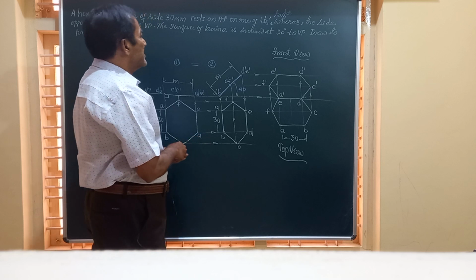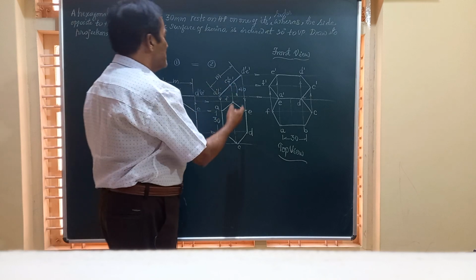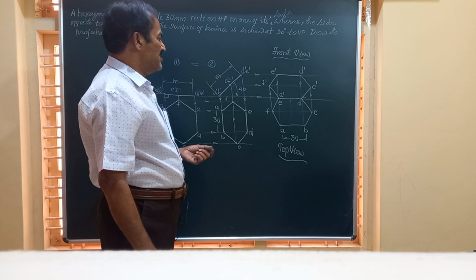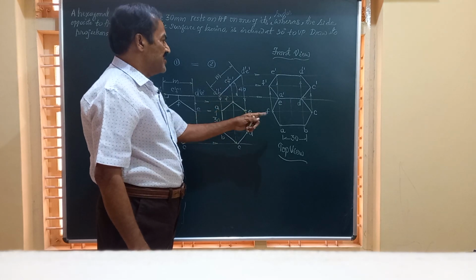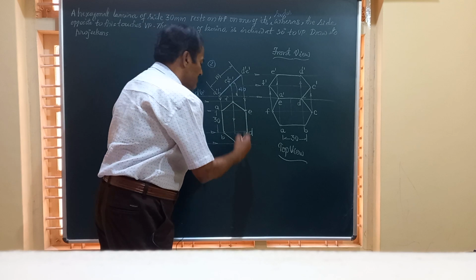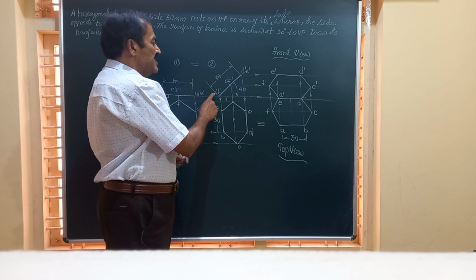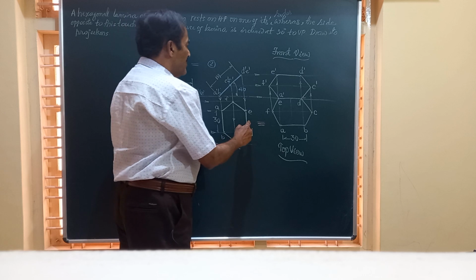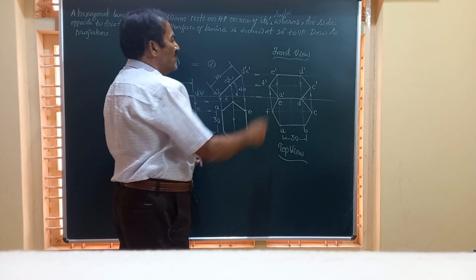Now friends, what does he say next? He says, draw its projections when the side opposite to the side on which it is resting is on VP. Friends, you can see here, the lamina is resting on side AB on HP. So we have to redraw this figure number 3 as figure number 4, such that the side AB, which is touching the XY line, should be parallel to this XY, and this D should be above the XY line.